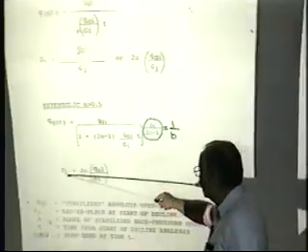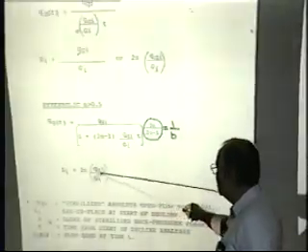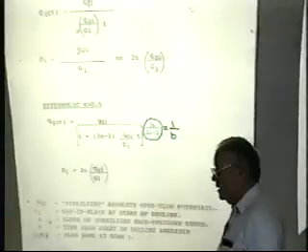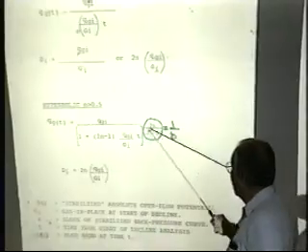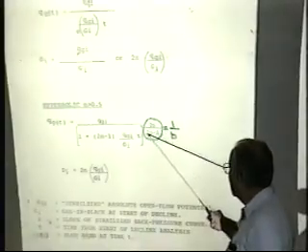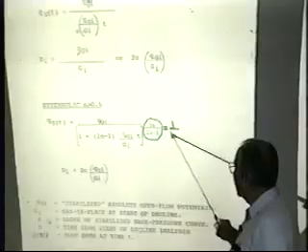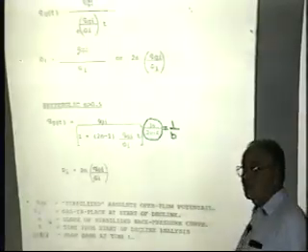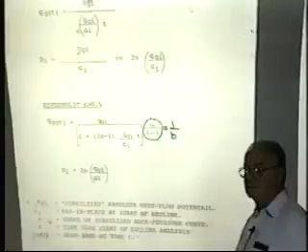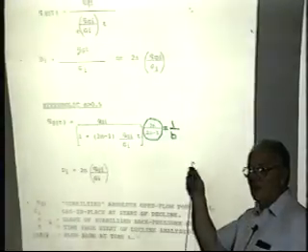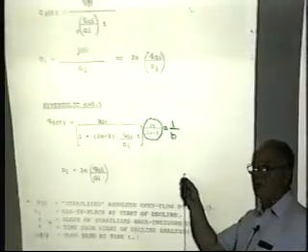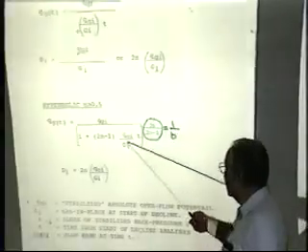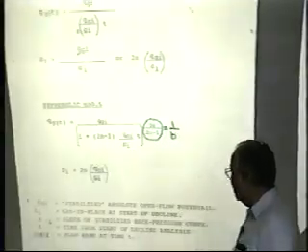As we go through here, the D sub I is 2n over QGI over G sub I, where n is the slope of the back pressure curve other than 0.5. 2n over 2n minus 1 is equal to 1 over b, so I can relate b to the slope of the back pressure equation. So I'll either calculate the slope from reservoir parameters where I don't have performance data, or if I have performance data, I can predict the value of B and I can predict the value of D sub I.